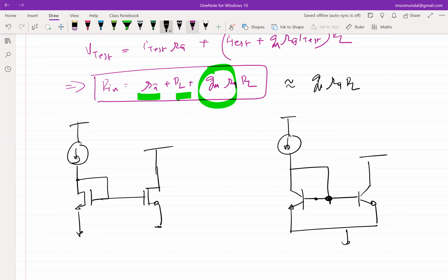In case of a MOSFET, we had connected drain to gate, just like that, because one of the reasons was we wanted to get this magic voltage, so that we can copy that voltage n number of times if we require. But that was possible because wherever we connected, it was not drawing current. Had it loaded, then this voltage would have dropped, so it wouldn't have been the magic voltage that we want.